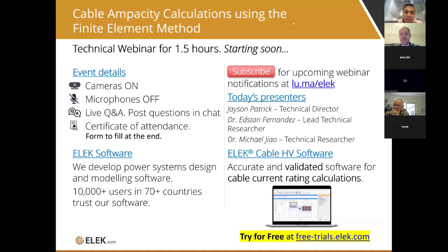Thank you. Okay, Edson, so just briefly, what are the limitations of the IEC analytical methods? When should we use FEM? Yeah, the IEC methods, basically the analytical methods, are restricting you to certain cable types, certain cable formations, certain configurations. For example, you can have only one duct.